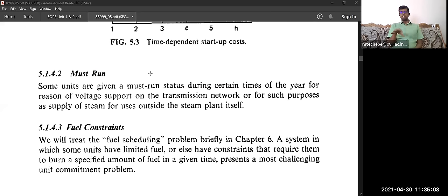It depends on the penstock size, the dam location, and the amount of water present in the particular dam, high head dam or low head dam. Low head means up to about 90 feet, and higher means greater than 120 to 150 feet. It depends on the amount of water, so they can easily turn on and turn off.